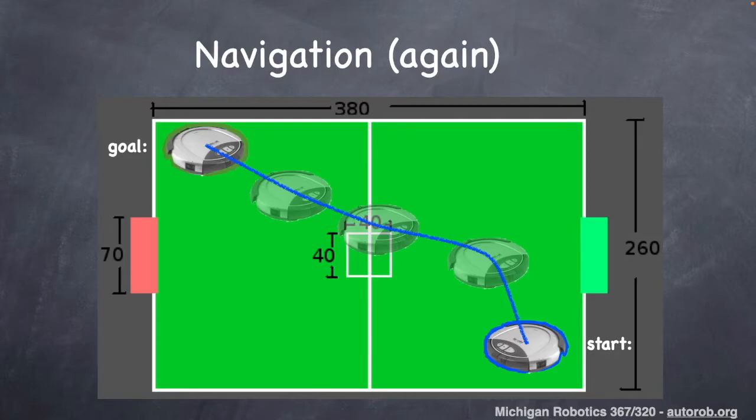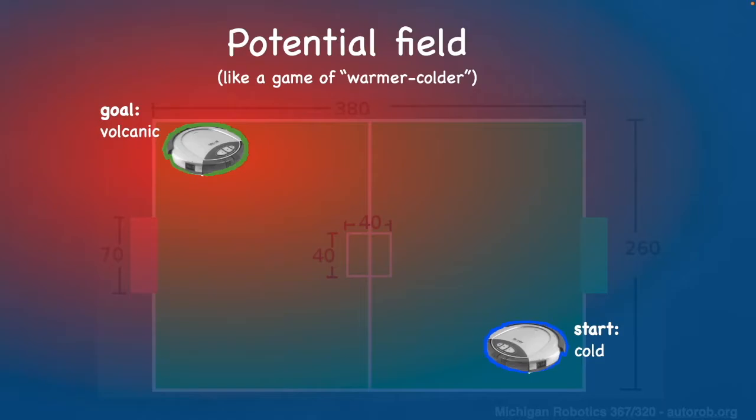And so if we wanted to apply a potential field to this planar space in order to define this motion plan, one way that we could think about that is by defining it in terms of warmer and colder locations in the space. Similar to how in the marble example, by changing the orientation of the board, the human was able to direct the marble in one direction or the other at each instant, our potential field is going to define a similar desired change in configuration at each individual point within the plane.